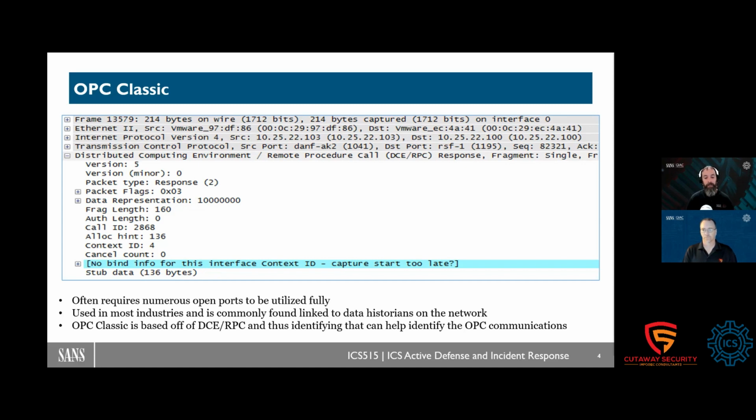Again, moving to that secure mode or secure protocol, I think, is a really good thing, but make sure you've got that justification in place to say, look, this is part of that insurance policy. Hey, we want to make sure we're doing things a little bit better, closing our aperture on our firewalls. We see that quite a lot in our OT engineering practice: hey, look, these firewall rules are pretty wide open.